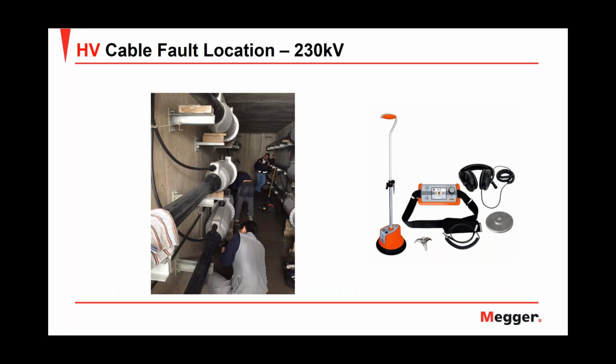Then, when I was done with the prelocation, I used the Digiphone, the pinpointer, to pinpoint the fault. And if you take in mind the place of concrete, the Digiphone did a wonderful job, because even under such conditions, the Digiphone was able to pinpoint the fault, and I confirmed where the fault was.